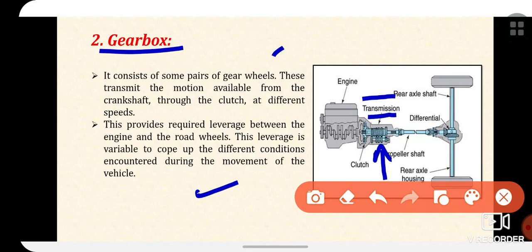Then the engine provides its highest torque and power outputs unevenly across the revolution range, resulting in a torque band and power band. Then the dynamics of a car vary with the speed. When moving at low speeds, the acceleration is limited by the inertia of the vehicle's gross mass. The wind resistance becomes the dominant barrier when the vehicle is at cruising or maximum speeds.